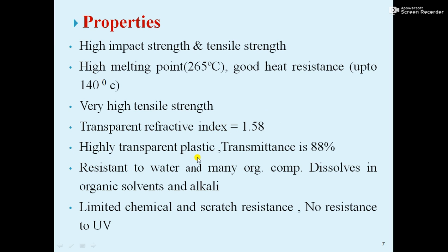It is a highly transparent plastic and transmittance is 88%. This property is very important, that's why it found use in optical articles also. It has resistance to water and many organic compounds, and it dissolves in organic solvents and alkali. So it has very good heat resistance, 140 degrees centigrade.